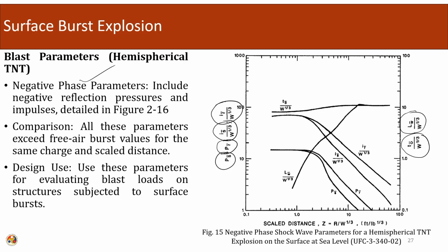All these parameters exceed the free air burst value for the same charge and scale distance. If we compare the free air burst with the surface burst, all these quantities in the surface burst explosion will be greater than the free air burst quantities.